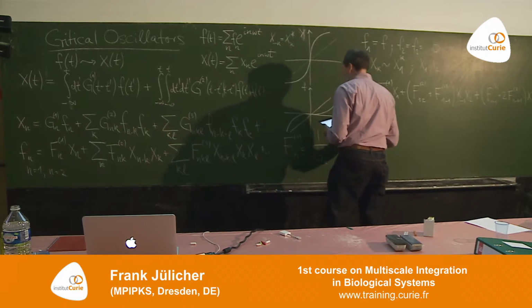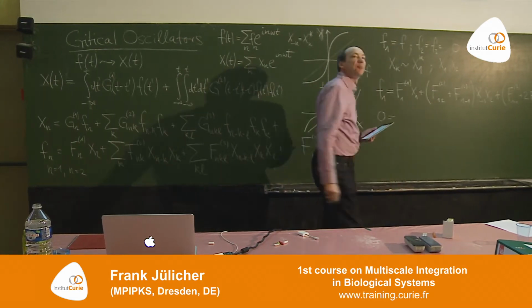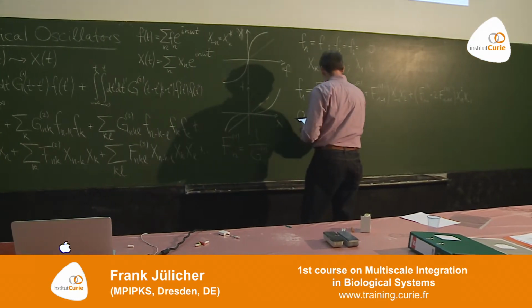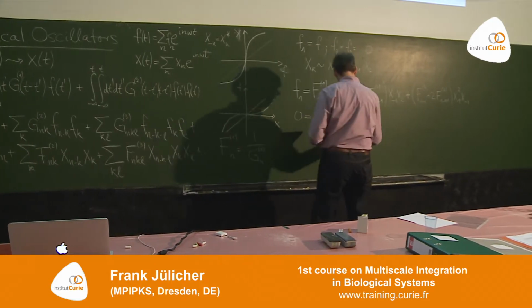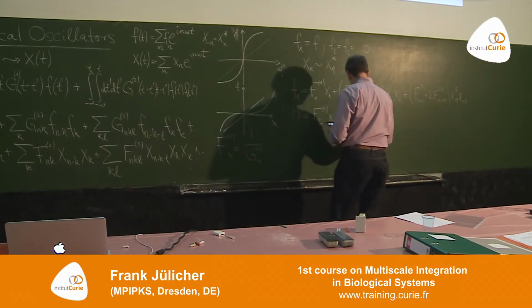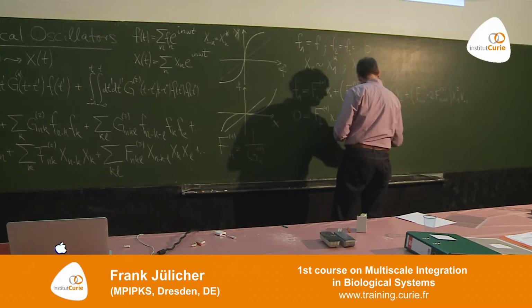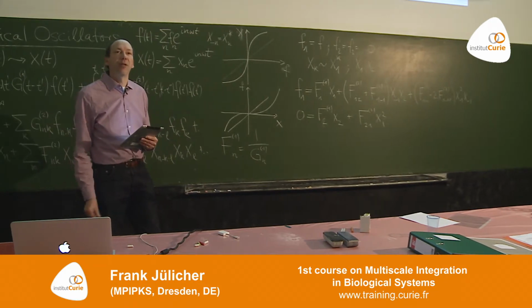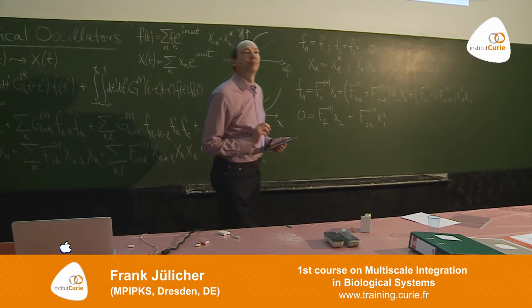Now the second equation for n equals 2, for the mode x2, starts with 0 force because I use a sinusoidal stimulus here. There's no second harmonic in the stimulus. Then I have here the linear term for the second mode x2, and that's very easy. There's only one term remaining. All the others are higher order and can be neglected. There's a coupling term F2 2 1 1 times x1 squared. So this is now two coupled equations for x1 and x2 for a given force, valid in the limit of weak stimulus.